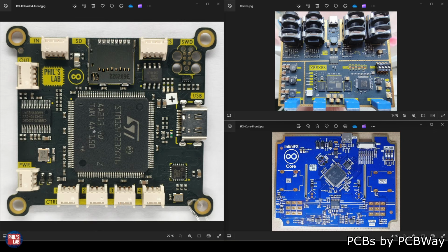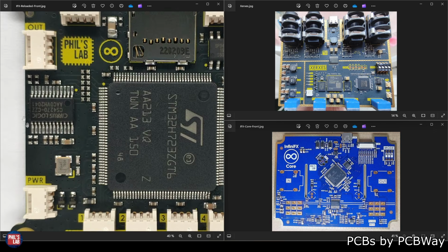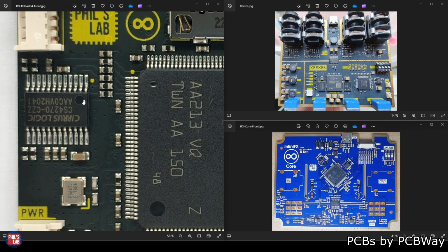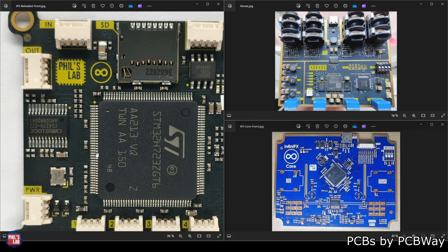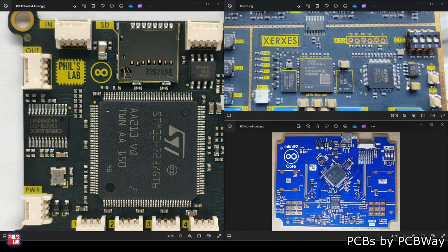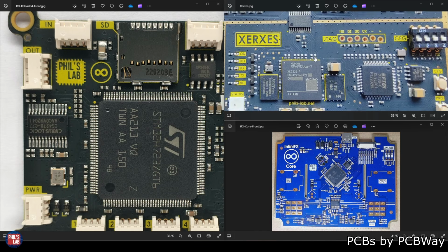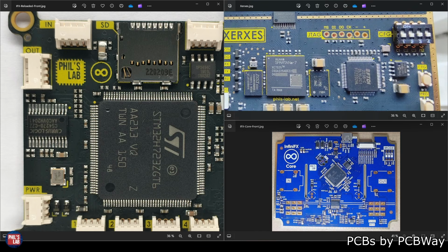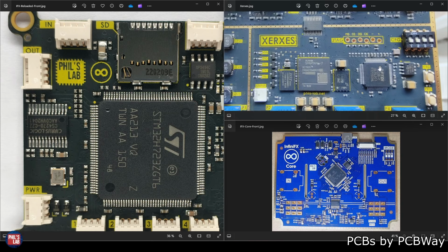For example, the board on the left hand side, we have an STM32H7 microcontroller in the center, and that controls various registers and the setup for a codec on the left hand side, which contains ADCs and DACs. Similarly, on the top right-hand side, we have this Spartan 7 based DSP board, and that has various I2C interfaces, again to the codec, but also, for example, as storage to an EEPROM, which contains an I2C interface.